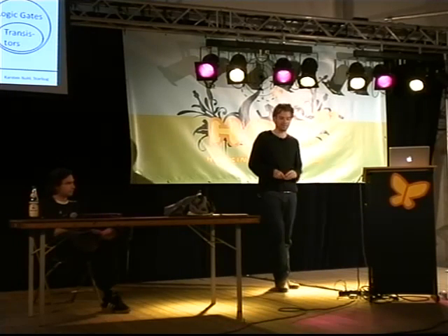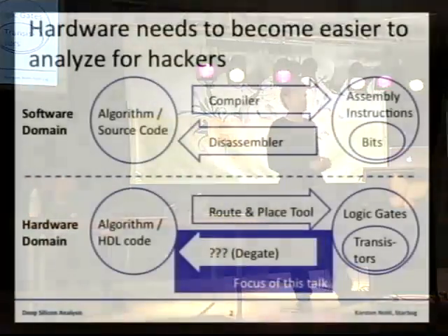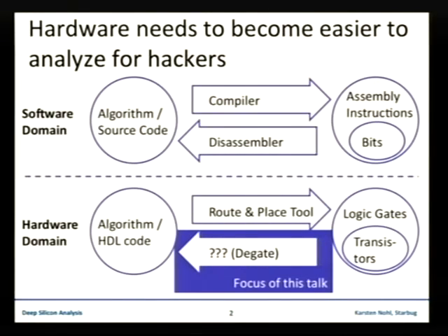In the hardware domain, however, this reverse way unfortunately doesn't exist yet. There is a similar design process in which a designer creates some source code in different programming languages, but still pretty much just hacks the design into a computer and then compiles it with a place and route tool into an actual chip that is being built from logic gates, which in turn are built from transistors. Now, the reverse mapping is what we want to provide, and we'll be releasing bits and pieces of it today, and hopefully enough for some of you to get involved without deep hardware knowledge at reversing hardware.